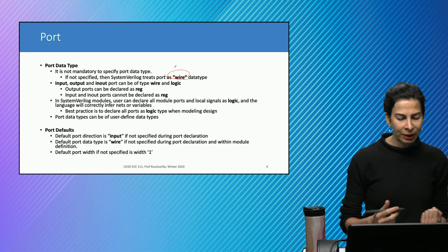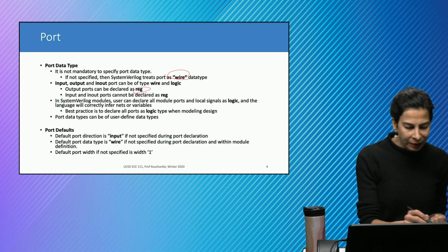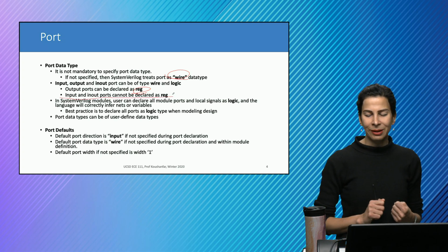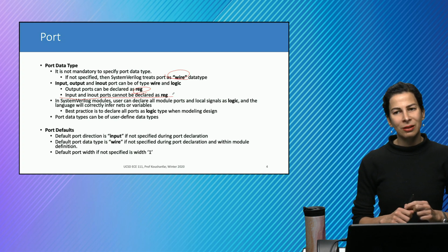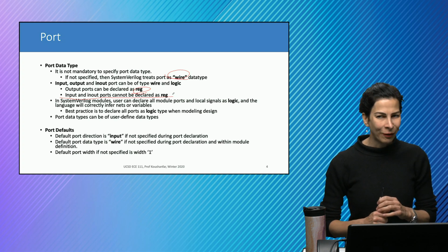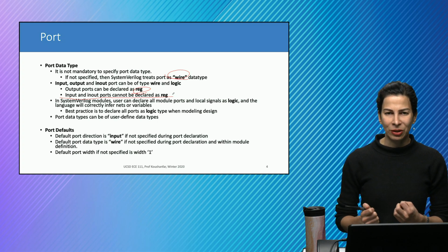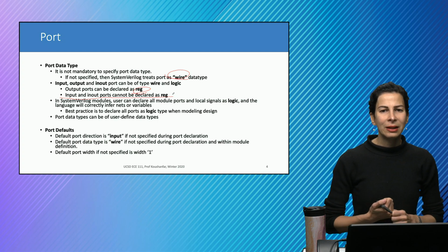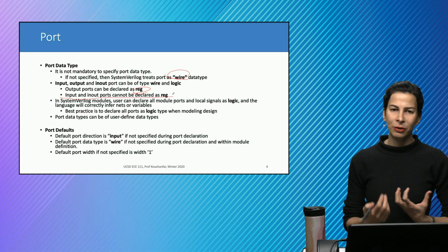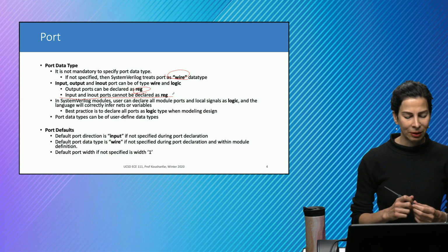You could also declare output ports as a register, but you cannot declare in-out and input ports as register. However, to reduce this confusion, as we discussed earlier, it is recommended that in SystemVerilog you use logic instead of register. When you declare logic, you don't have this confusion or double checking of the input ports and getting the errors.